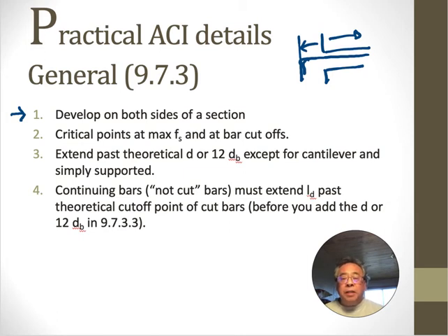Anywhere you think you can stop the bars, you have to go an extra d or 12 bar diameters, whichever is greater, except of course at the end of a cantilever or a simply supported beam. Right? You end there. You cannot extend. We talked about this. You cannot extend that bar out into the air.